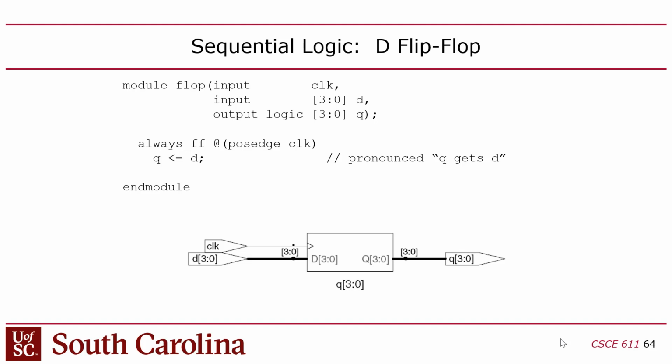If you don't do that, then you end up with a combinatorial loop where the control unit says stall, and so you stall it immediately, and the branch turns into a stall. And you're like, oh, I don't need to stall. Don't stall. And then it turns back into a branch. And you say, oh, it's a branch, I need to stall. Stall turns back into a stall. And you get into this combinatorial loop,